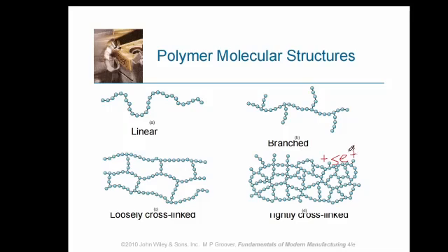They are not able to withstand repeated heating and cooling cycles because they react chemically and form char. But the loosely linked structures result in elastomers, rubber or thermoplastics, which are able to be heated and cooled in repeated cycles without degrading.